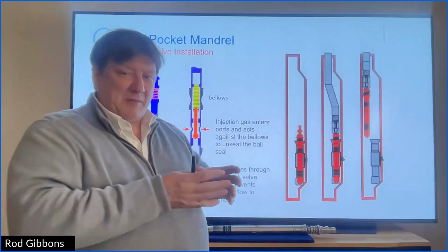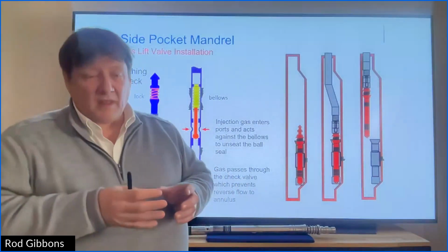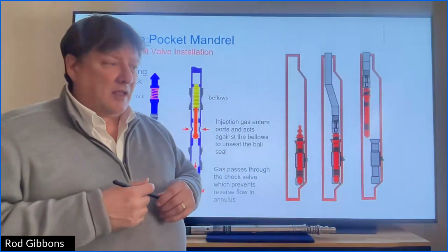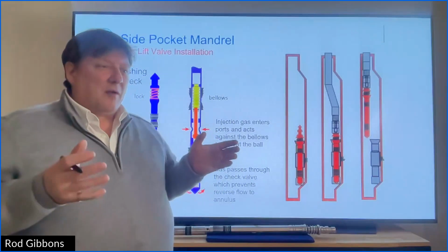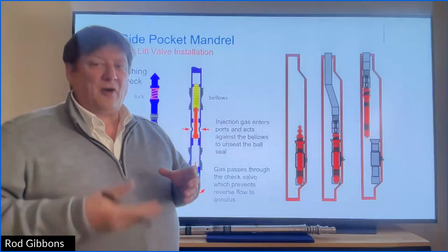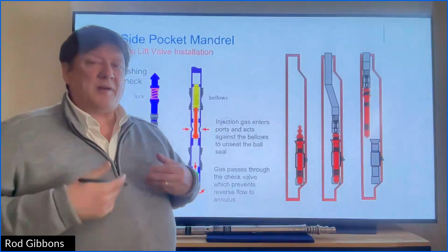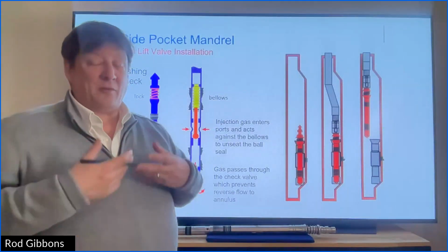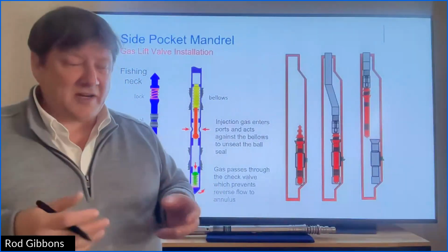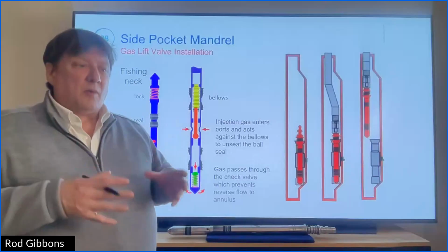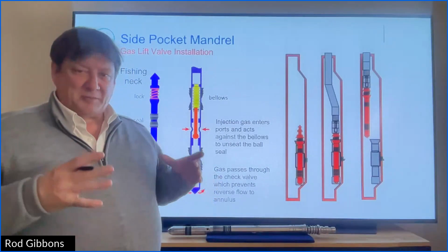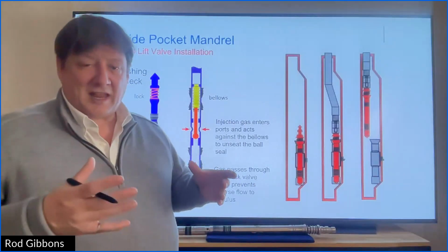I want to keep them in the tubing. The primary reason is well construction: for pipe that is seeing flow from the reservoir, we want to be able to change that out. If it wears out, or has an issue with the chemistry, we can always change it out. We want to keep reservoir fluids away from the pipe that is permanently in place, such as casing.